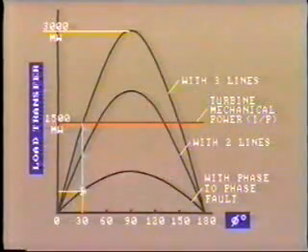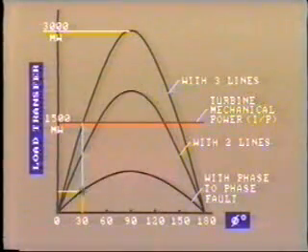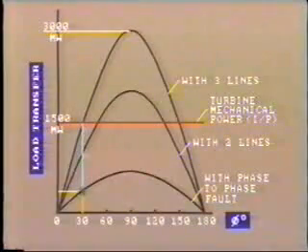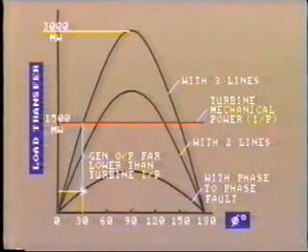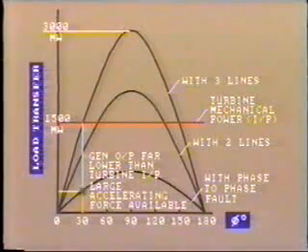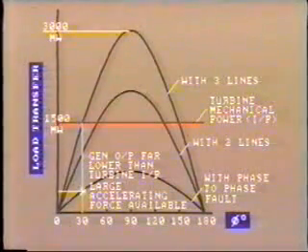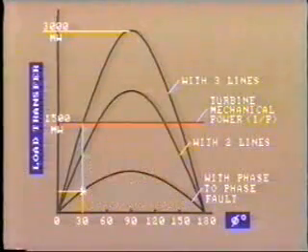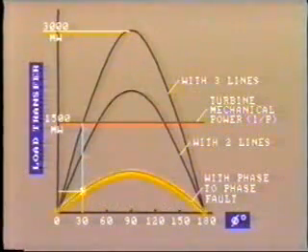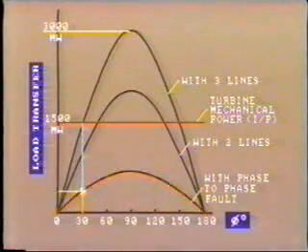At the moment the fault occurs, the power output falls drastically to this point on the fault curve. At this point, the generator output is far lower than the turbine input, so that there is a large amount of accelerating force available. As long as the fault remains on, this particular curve indicates the condition.